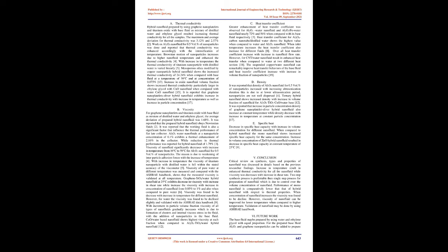17. Viscosity. For graphene nanoplatelets and titanium oxide with base fluid as a mixture of distilled water and ethylene glycol, the average deviation of the prepared hybrid nanofluid was 1.68%. It was reported that the prepared hybrid nanofluid obeys Newtonian fluid behavior too.